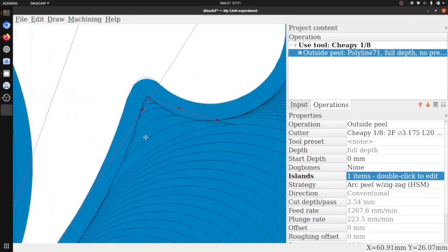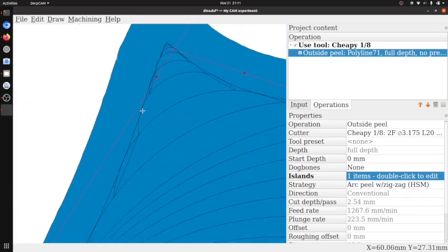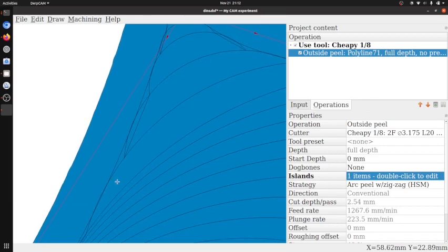So you will notice there's a line parallel to the edge of the part. This is actually a cleanup pass. After DerpCAM finishes doing one of the HSM operations, it actually runs the end mill all the way around the edge just to tidy up any of these little loose triangles. Things much smaller than the minimum step over size of the algorithm. You will notice that occasionally the algorithm does just slightly overlap this finish pass.